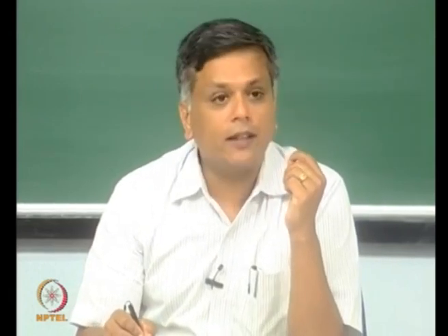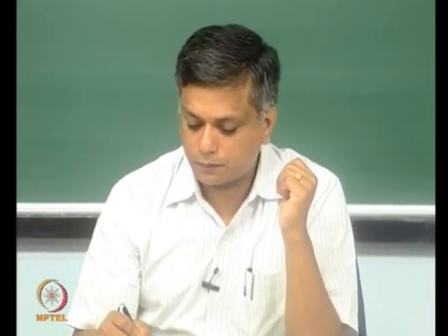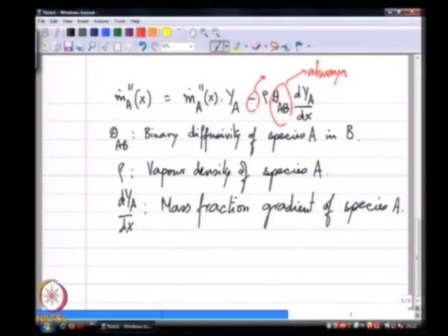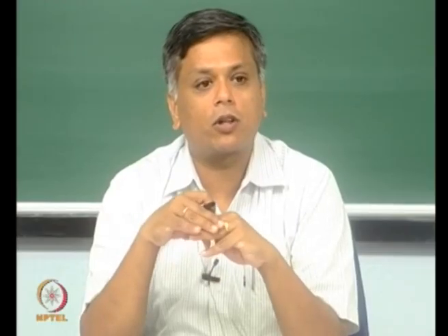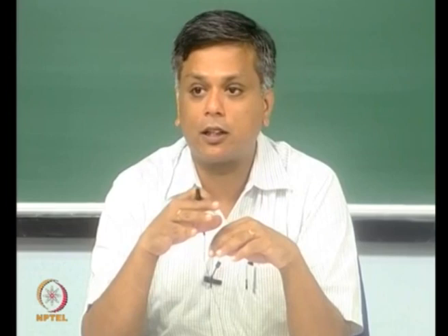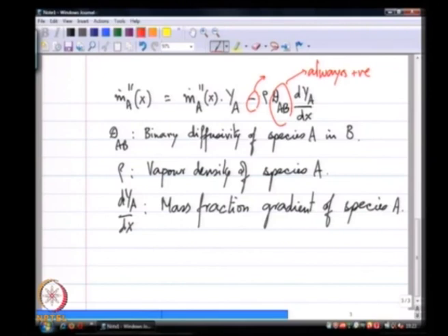Another way of thinking about it is to ensure that your diffusivity is always a positive number in any equation, whether it is your heat conduction equation, mass transport equation, or momentum transport equation, which is basically viscosity. All these diffusivities can only be positive numbers, because you have already taken care of the fact that if the gradient is negative, flux is positive by putting this negative sign. This comes from your second law of thermodynamics. You take your Carnot statement of the second law of thermodynamics, and when you rephrase it in a diffusion process, mass, momentum or heat, the diffusivity has to be a positive number.